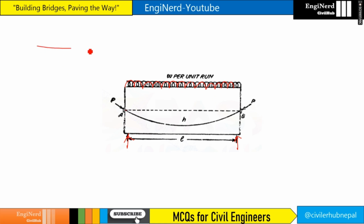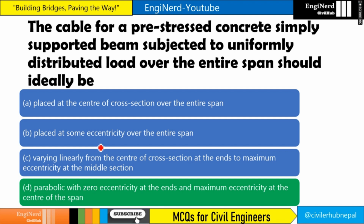So we know that the bending moment of the simply supported beam is like this, right? So the curve of the pre-stressing steel should resemble the bending moment diagram, such that it can be effectively used. So our answer is parabolic with zero eccentricity.